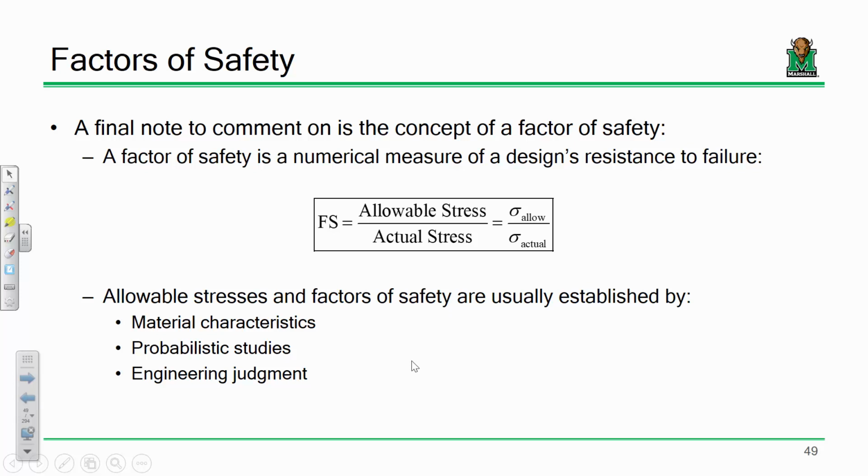It's not that uncommon to use factors of safety of 3 or even higher in geotechnical engineering applications, because when you're designing a retaining wall or a foundation, soil properties are so highly variable that we end up bumping up our factor of safety like crazy just to account for that. Whereas, in structural engineering applications, we might use less of a factor of safety because we're more certain about how our elements are going to behave. So it just depends. There is no answer.